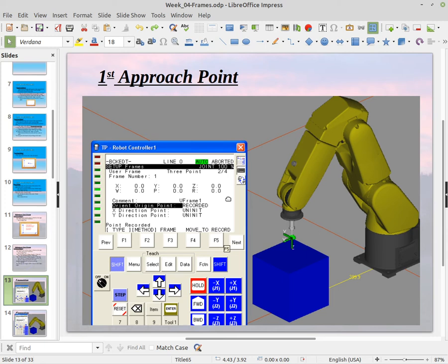And that is the faceplate of the robot. So remember, the faceplate is where the tooling actually mounts on the robot. So by default, the user frame is the center of the faceplate. And so then what we would have to do is come in and choose the method. So we could come in here at 2, press F2 to choose the method to teach. And this method, we would have our choices there of 3-point method, 4-point method, or direct entry method.